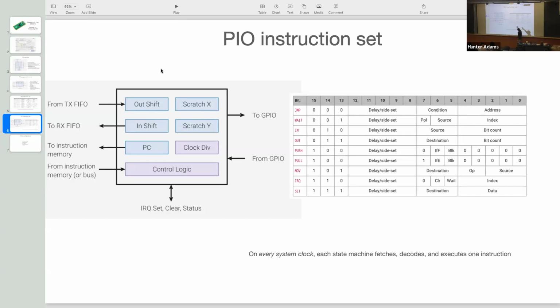The other instructions that would fall into the category perhaps of program flow include the wait instruction. Wait says, please step through my program, and when you hit the wait instruction, stall. And when some condition is met, and you get to specify what that condition is, we'll look at what your options are. When that condition is met, then continue on.